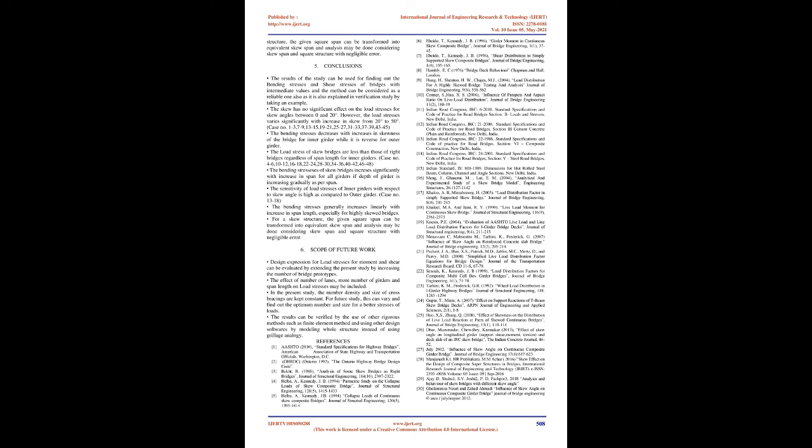5. Conclusions. The results of the study can be used for finding out the bending stresses and shear stresses of bridges with intermediate values, and the method can be considered a reliable one, as it is also explained in the verification study by taking an example. The skew has no significant effect on the load stresses for skew angles between 0 and 20 degrees. However, the load stresses vary significantly with increase in skew from 20 degrees to 50 degrees.